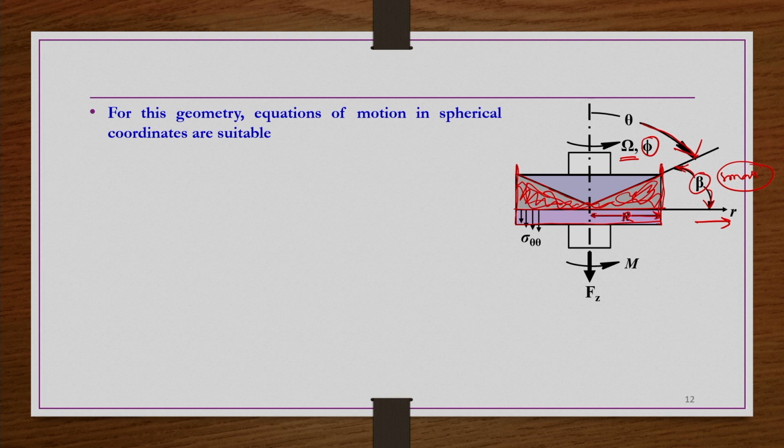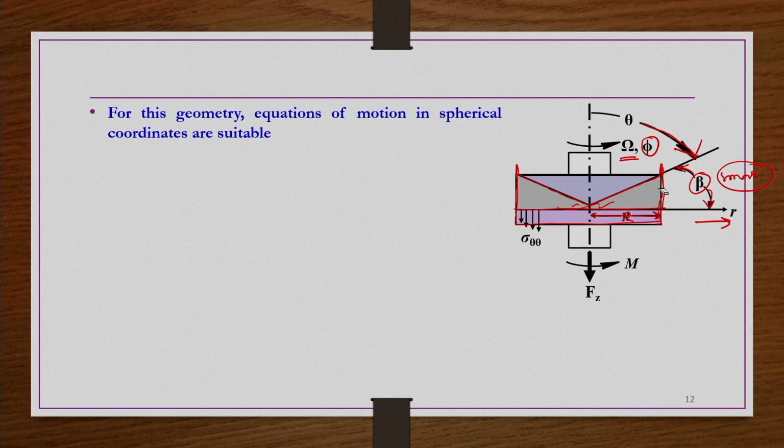When the cone is rotating, deformation in the fluid will take place because of the rotation of the cone. Okay. So now once there is a deformation, the corresponding shear rate and corresponding shear stress we have to measure. Since the cone angle is very small, in general the cone angle is taken very small, so that the shear rate is constant.